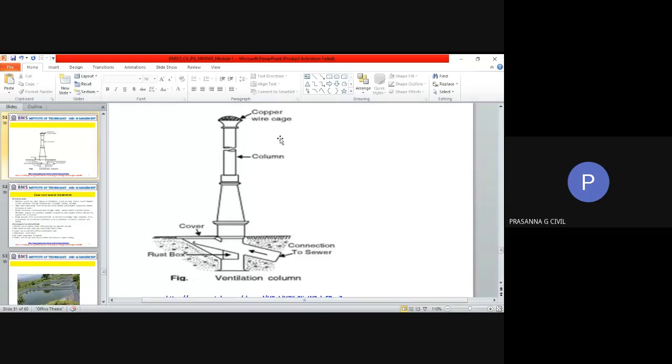You can get the ventilation done properly by laying the pipeline properly, by providing manholes with vents, by providing ventilation shafts, etc., so that the release of these gases can be done properly. So that is with respect to laying, testing, ventilation. And commonly all these things are grouped together. Okay, so that portion is over with respect to ventilation of sewers.